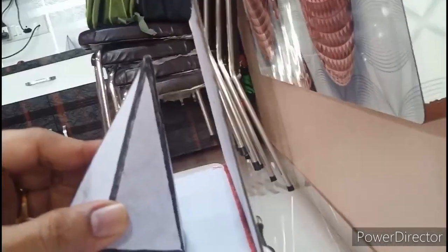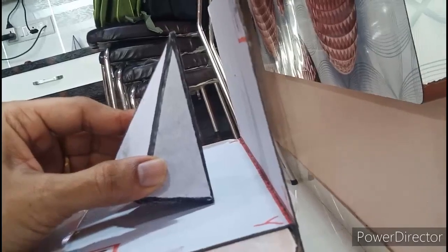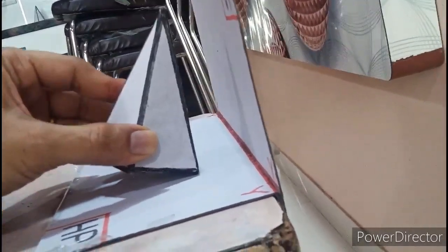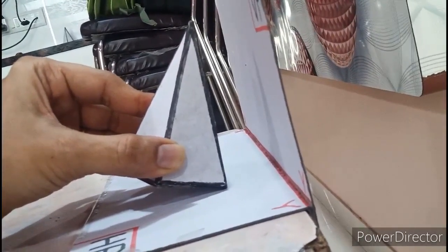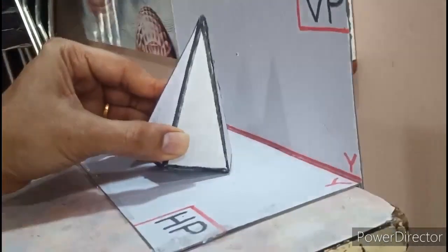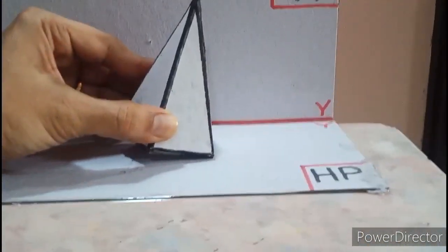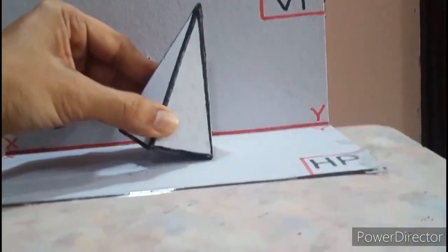Now we should develop that skill of breaking this third stage, or converting it into the second and first ones. As we discussed, in the second stage the axis has to be either parallel with HP or VP. So we will turn this diagram by 90 degrees, and we'll make only the triangular surface perpendicular with HP, as you can see here. So the base is still in the air.